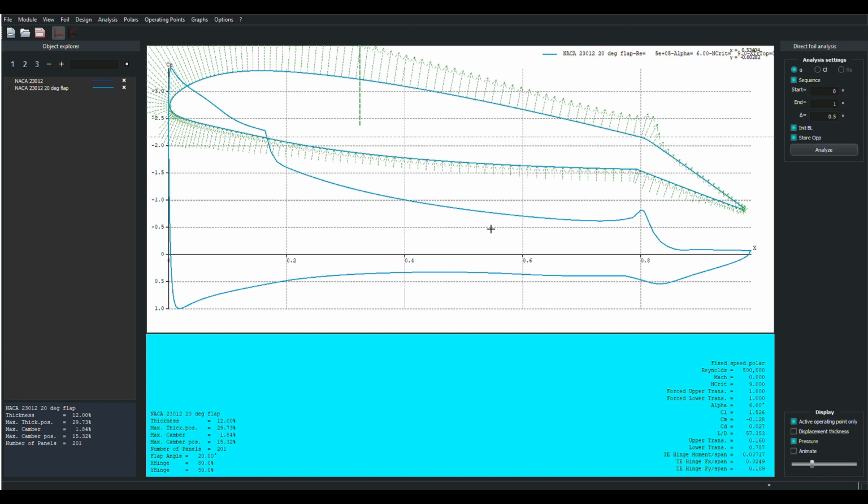Likewise, if it's an aileron function, we get a nose down pitching moment, but we also get a tremendous rolling moment because it's out at the tip, and we're generating a bunch more lift up front here. And all of that lift is trying to lift up the wing and make you roll. And if this were the left wing, that would make you want to roll to the right. Okay, we're not showing drag or anything here. We're ignoring that for the time being because it's not germane to our discussion. Now you remember we talked about the poor molecules having to beat their way into this adverse pressure gradient.